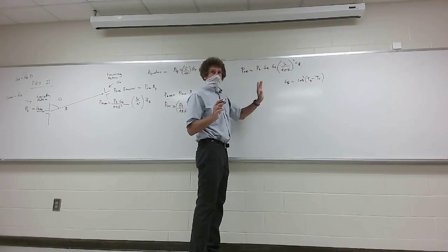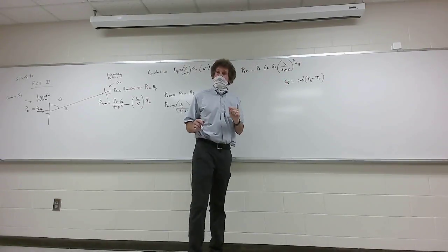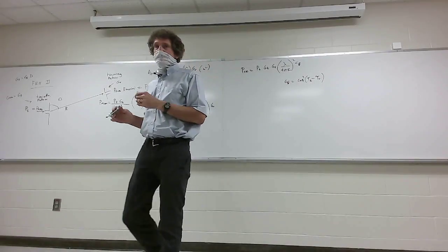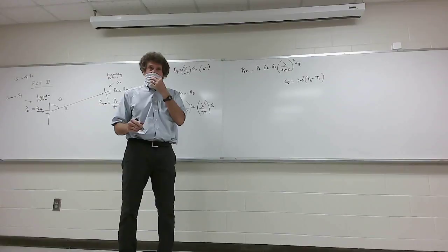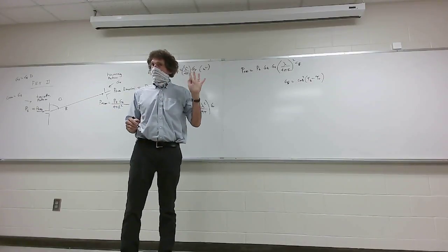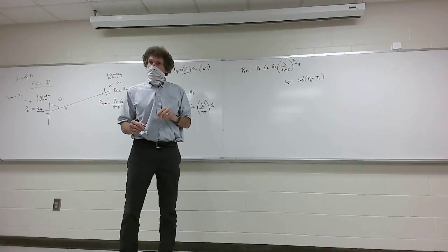So that's just the efficiency right here. Now, I don't worry that much about efficiency. Sometimes in the real world you have to. But this power, and here's the thing I want you to know: that received power is not how much you can get if you put a load on that second antenna. At most, you can get 1/2 of that. Do y'all hear me? Now here's why.